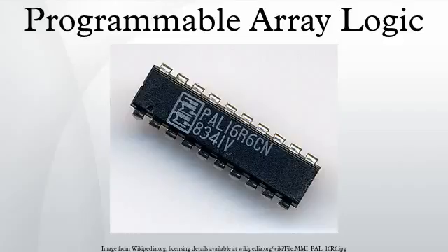The number of product terms allocated to an output varied from 8 to 16. This one device could replace all of the 24-pin fixed-function PAL devices. Members of the PAL-V series included the PAL-16V8, PAL-20V8 and PAL-22V10.